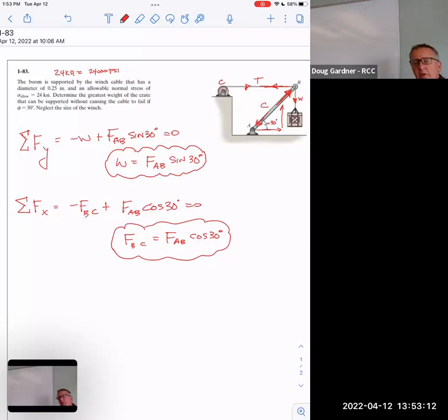Okay, what did you say? Go back to your Y equation and solve for force of AB, which is W divided by sin of 30, and then go to your second equation, plug that in, and then you'll be able to solve for the weight of the box. Because you know the force in the BC, or at least the max force. Yeah, the cable. Yeah, and I noticed I got the cable in 2 different places. So that's kind of interesting.